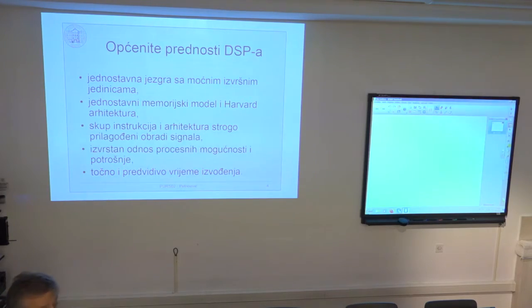They have 3 DSP processors that are implemented on the same silicon. They share the common memory space, all of these CPUs, and of course they have some kind of local memory in order to be able to execute in parallel. So each of these cores has some cache memory within the actual CPU architecture, so they don't have to go to the common memory to fetch instructions and data, as long as this data access is limited to the size of this cache memory.